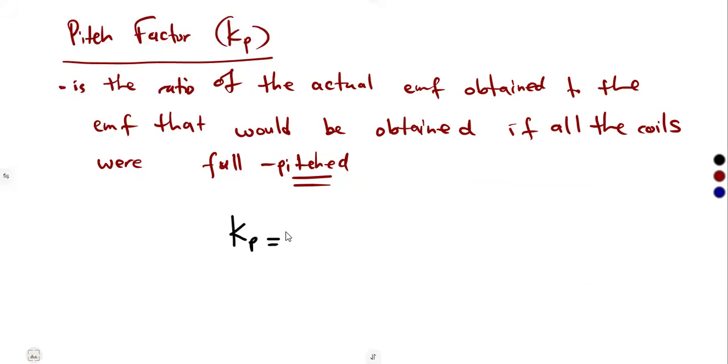So our pitch factor can be calculated, guys. We can determine this, which is also given in our formula sheet. Calculating the pitch factor, it is the cos of the angle of the short chord over 2.